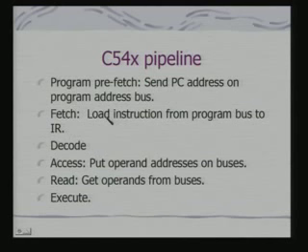Fetch is load instruction from program bus to instruction register, then decode. Then you have an access block, put operand addresses on buses, because these operands are also being obtained from memory. It is not just there inside the register. And then you read, get operands from buses, and execute.